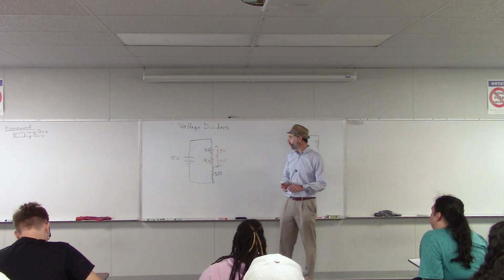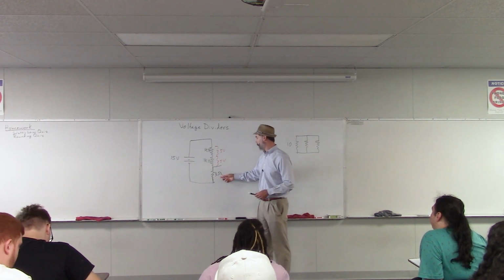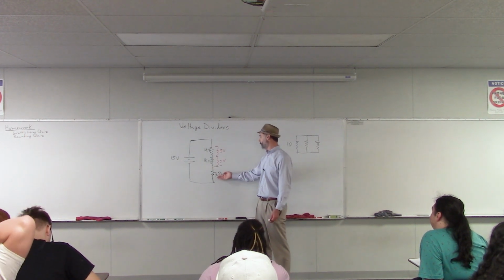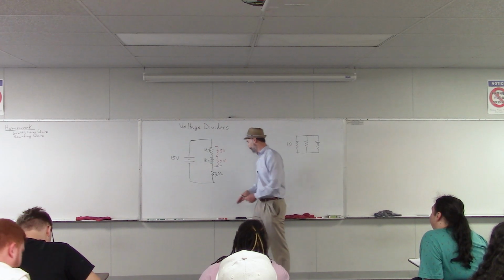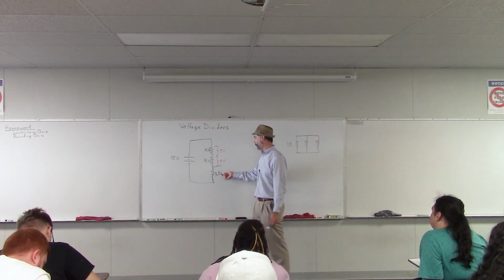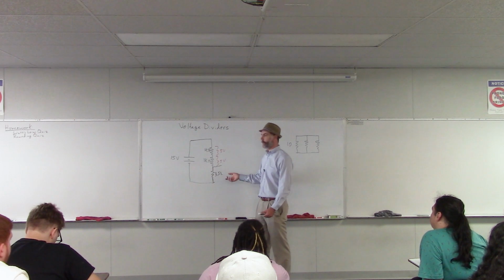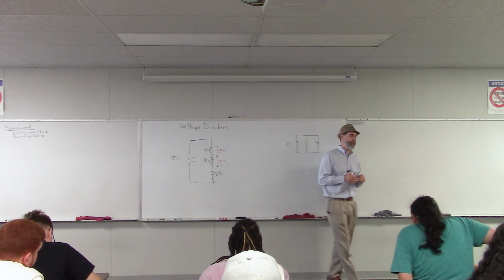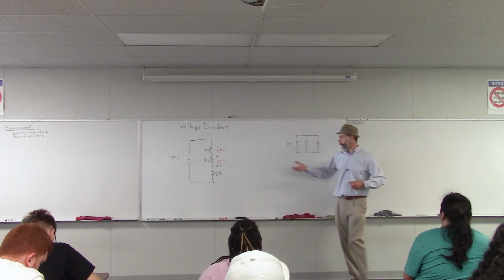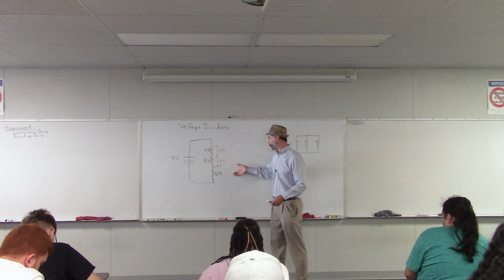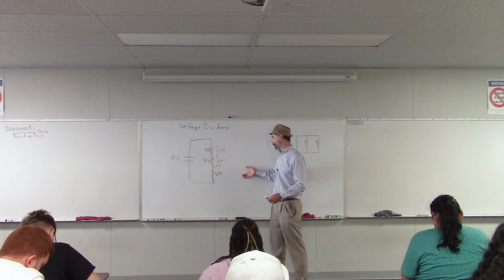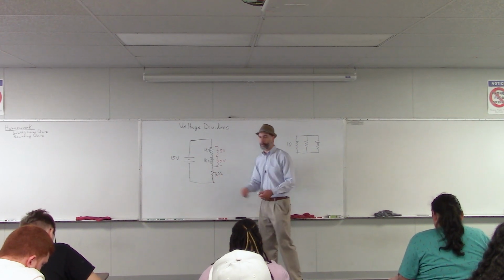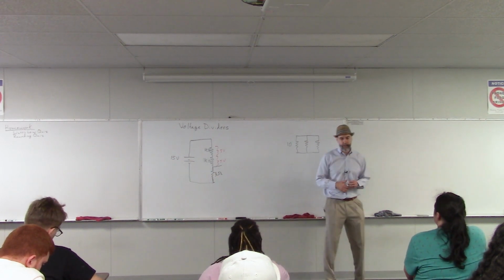No. This resistor down here is going to have much less than a third of the total resistance, so it's going to get much less voltage. This is going to get maybe a quarter of a volt or something like that, and the rest of the voltage would be up here. So the answer is no, you can't just treat it like a power supply, because if you put things that have low resistance down here that need a lot of power, basically it pulls this voltage down.